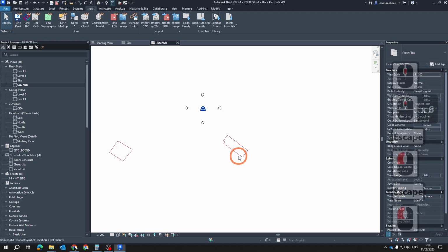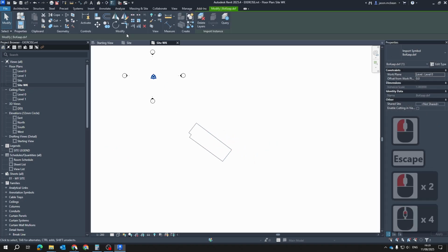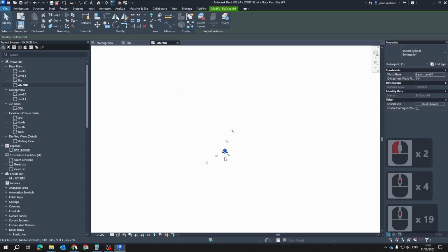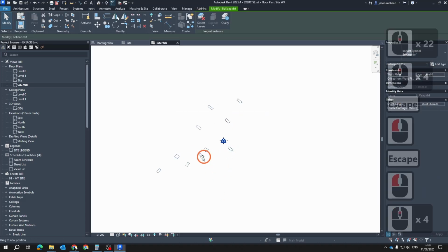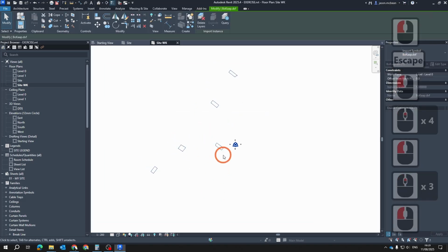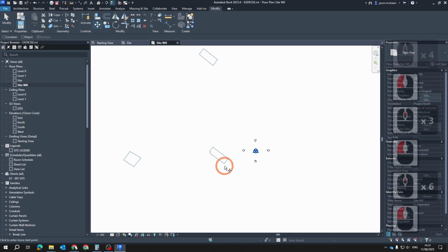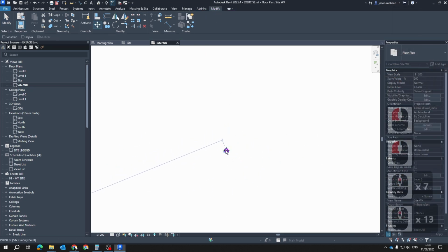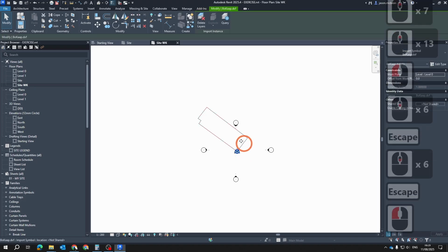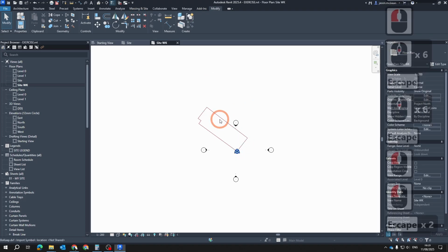Okay, so I'm going to move the DXF file. Now, generally, these are pinned. When these come in, you'll find that they're pinned. If it moves, it's not pinned, so that's good to know. So I'm going to move this to the right location. Just like that. Good. Then I'm going to pin this layer so it doesn't move around.